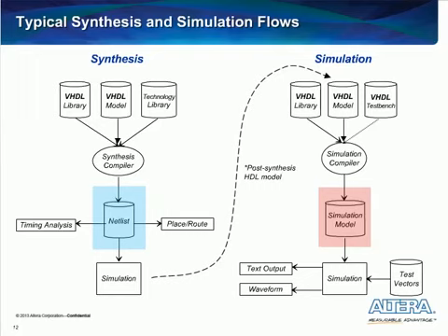During simulation, the tool takes any test vectors or stimulus provided by you and produces output waveforms or text files that can be used to verify proper operation. As an alternative, you can also write your simulation stimulus using generic VHDL code called a test bench. The test bench code gets compiled along with the design so that the stimulus is also in the compiled simulation model. This means you do not need to provide simulator-specific test vectors when you execute your simulation. The advantage of the test bench is that your stimulus is portable just like the design files.